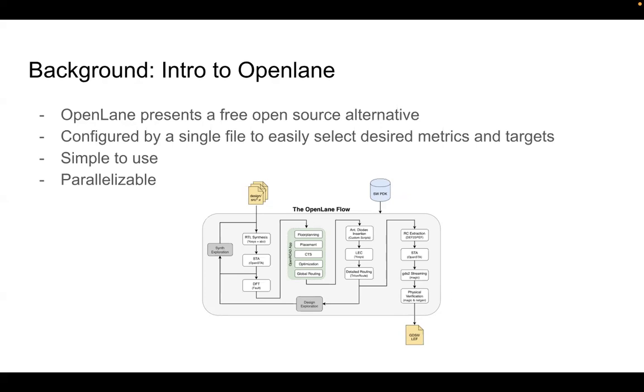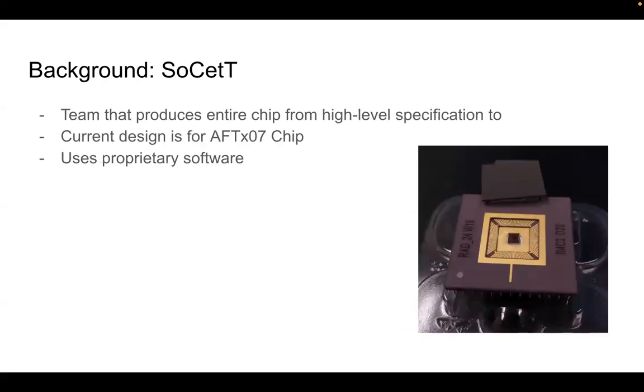It'll specify different metrics that need to go through, and you just run that and it'll take your entire design from start to finish so that hopefully it can be taped out in the end. Additionally, because they take care of a lot of that scripting, they've been able to make some of the steps parallelizable, so you can run it on multiple computers and multiple cores, so it can hopefully be faster than just running it on a single core.